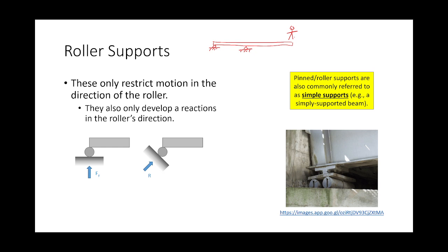the diving board concept. So here's a person on a diving board. They are applying a load downward. And so think, how does that roller, if this is the roller, how does it have to behave to keep the system in equilibrium? It has to pull down as well, right? Because if not, if I'm standing on the end of that diving board and that roller isn't holding it back, I'm going to go for a tumble, right? I don't want to go for a tumble. This is statics. We want to keep things stable, right? Does that make sense?